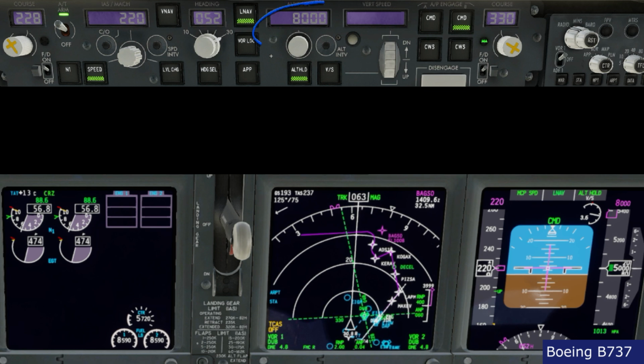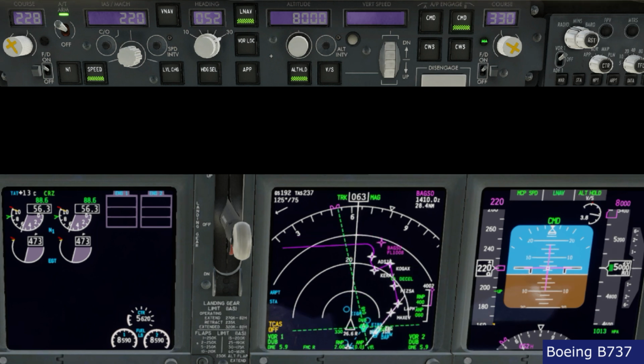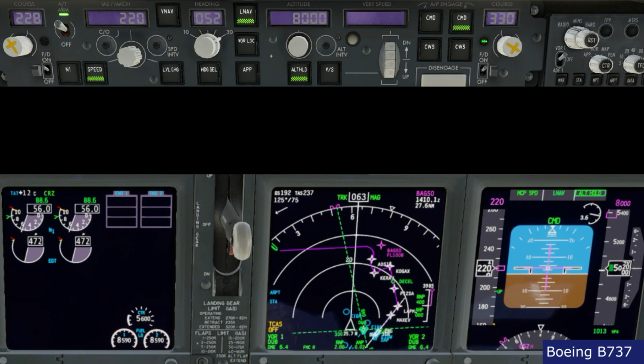So you see that what happens is that here I have selected a new altitude and I'm still in altitude hold, I'm still maintaining 5,000 feet, absolutely nothing happens. Well, I can see on the flight mode annunciator that automatically the system armed for me a vertical speed mode, meaning that if I turn the vertical speed knob, I can start climbing and descending directly in vertical speed. But if I go back to altitude hold, the aircraft is maintaining the altitude.